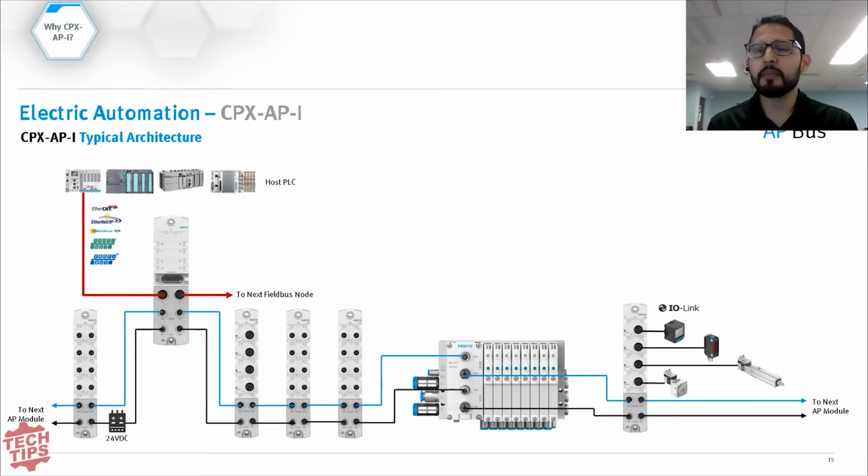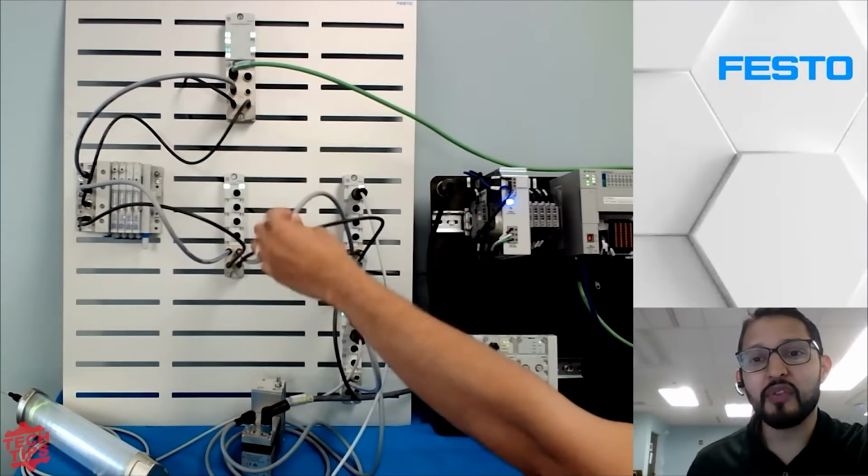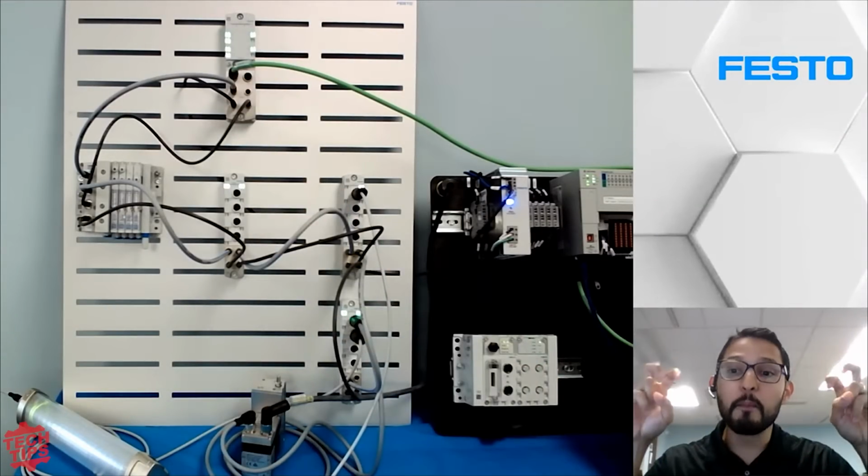It's basically like modules from other brands out there, for example, a PLC rack. Usually there's a backplane running on the PLC, and there's a communication bus running on the backplane that you never ever deal with. You usually set up Ethernet IP, and the rest is set up for you. In this case, it's the same approach, with the only difference that now you can see the cable for that communication, let's say, backplane.